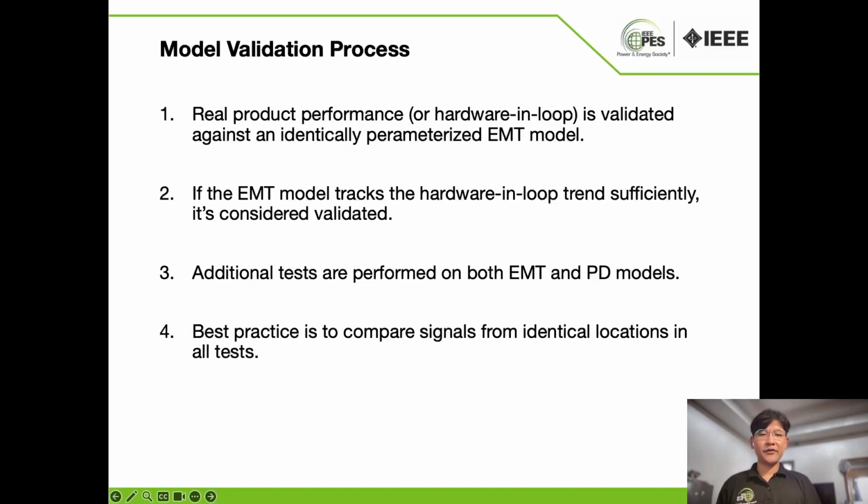Component model validations across simulation domains. For example, EMT against PD should have a comparatively wider tolerance for match, with any discrepancy explained. A difference in solution engine can produce slightly different yet still representative performance.